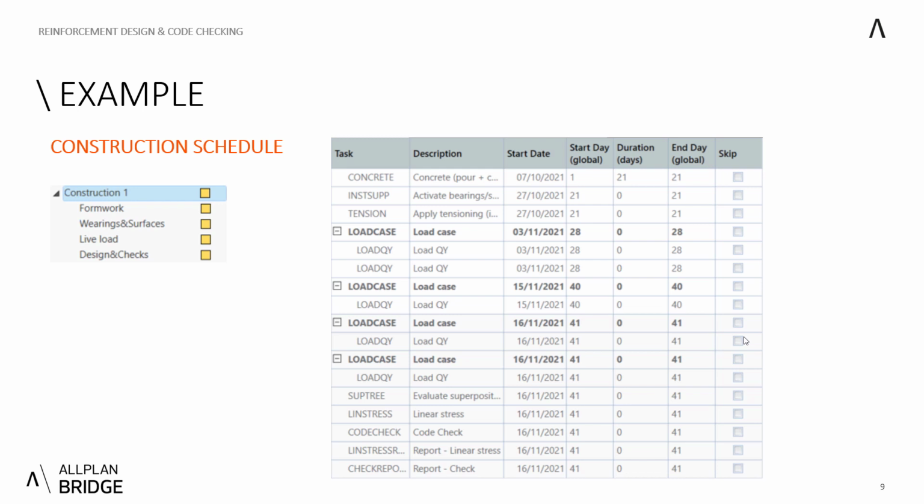And at 41 days, the construction is complete, and we start the final creep calculations. And therefore, it's also the beginning of service, where we apply those two load cases for the crowd, and then simply calculate the design and check tasks that we will speak about later.